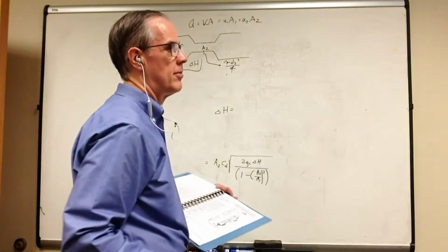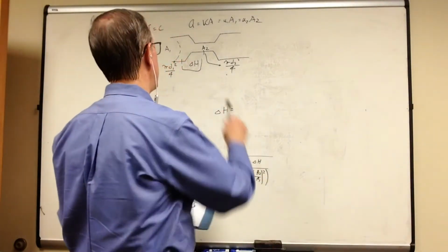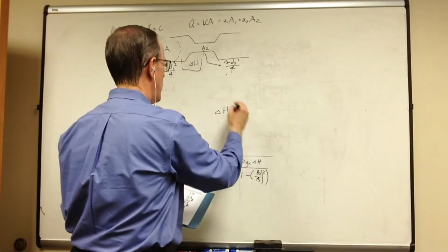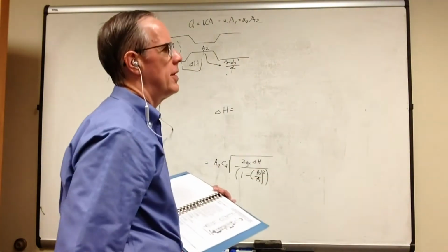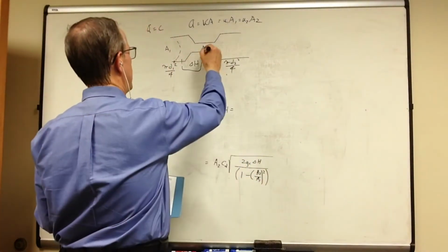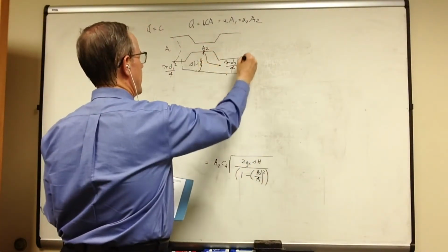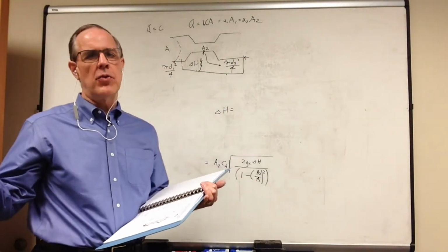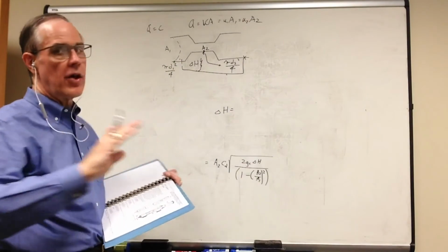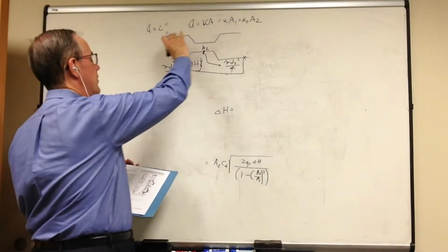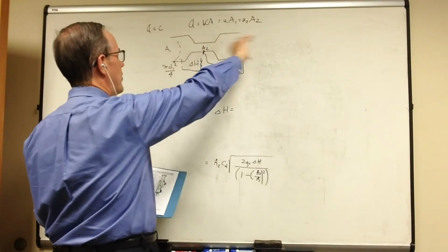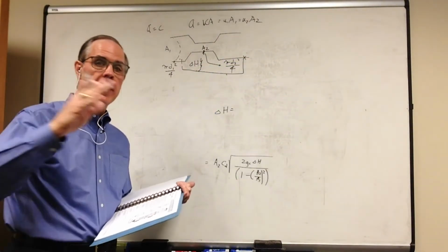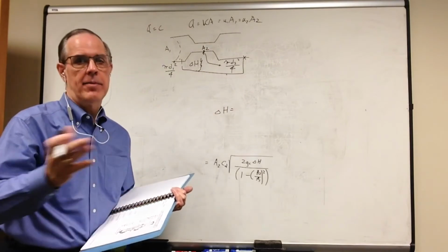The head loss, or delta H, the head change, not head loss, the head change in the system from point 1 to point 2. And usually with devices, the head change, instead of being here, it'll be over here. In the ideal world, if we didn't have any losses, by flow continuity the velocity is going to be the same, and we should have no delta H. But that's not true.